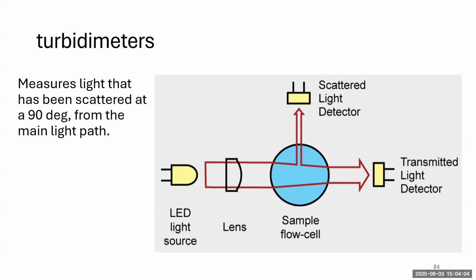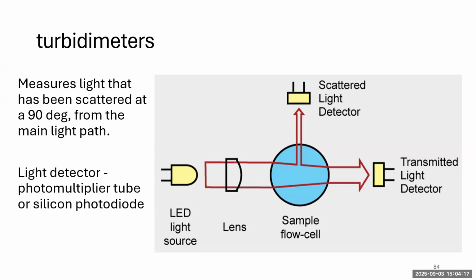And if we did find a way to detect them, we'd have to do a very involved laboratory process that wouldn't give us real-time results. But a turbidimeter gives us real-time results, and it can detect those very small particles. And you see there's an arrow pointing straight up. That's the reflected light at a 90-degree angle, and it's being detected by a light detector.